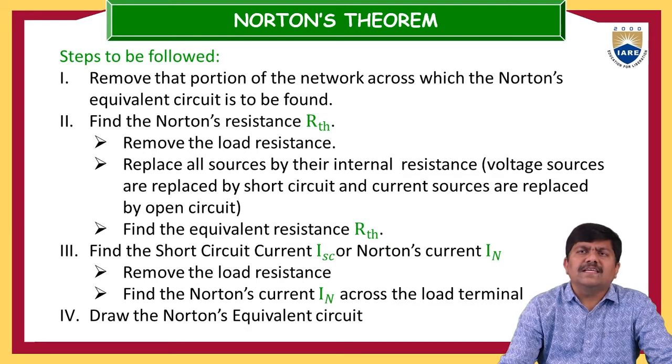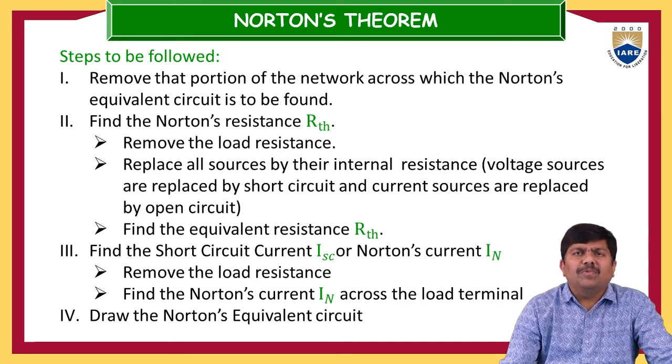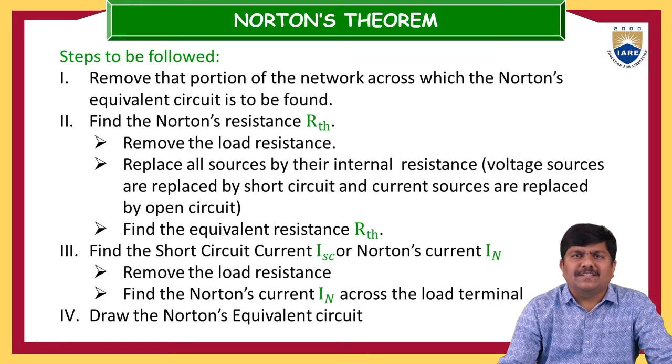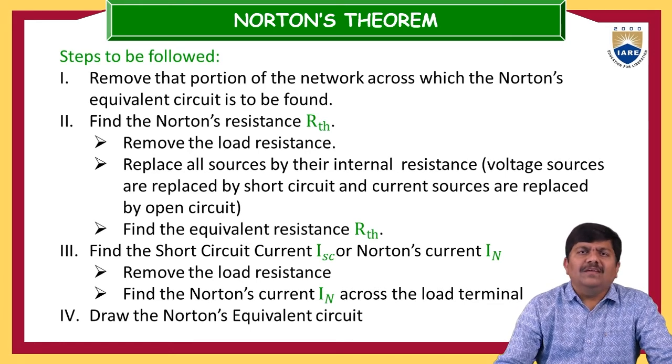Once we get the Norton's equivalent circuit, finally connect the load back to the network, and by applying simple principles, or if required, we can make use of the source transformation technique. Or directly, Norton's theorem can also be verified from Thevenin's theorem.